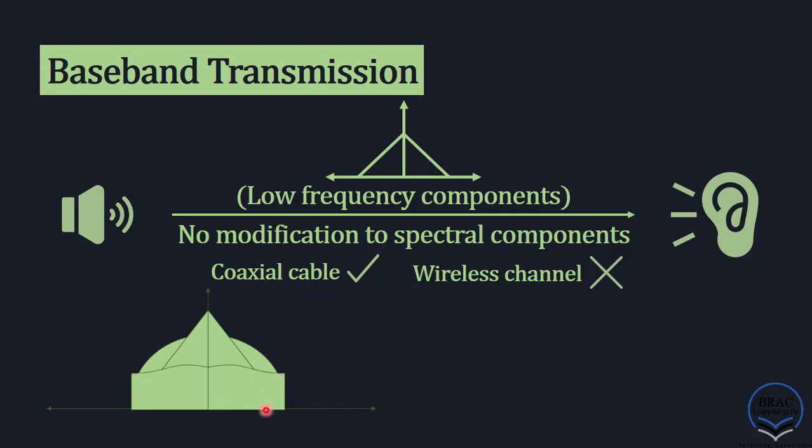And the third one, again, similar bandwidth. So we cannot actually differentiate these 3 signals in time or frequency domain. This is the lacking of baseband transmission. If you do not make any change or modification to the spectral contents, as they are human speech, they will be overlapping in frequency domain, and we cannot actually differentiate which signal is meant for whom.